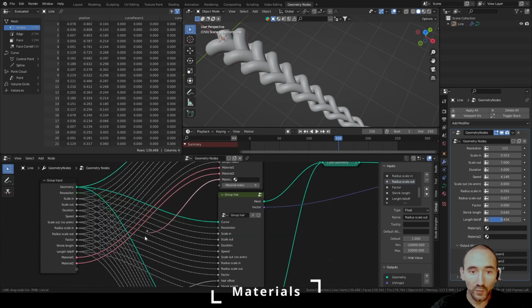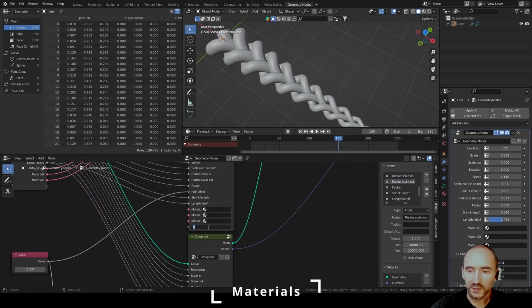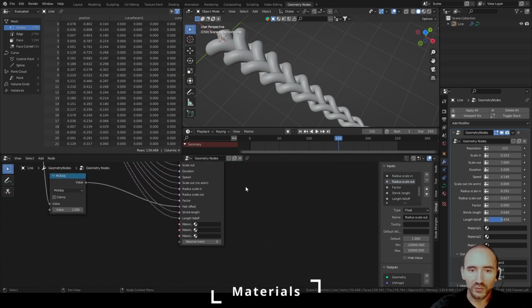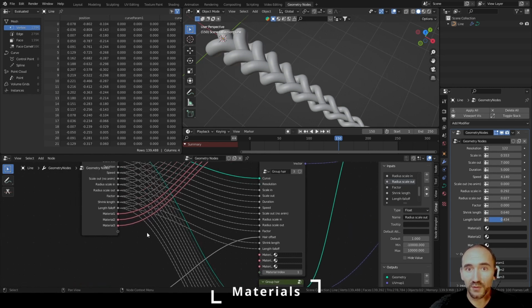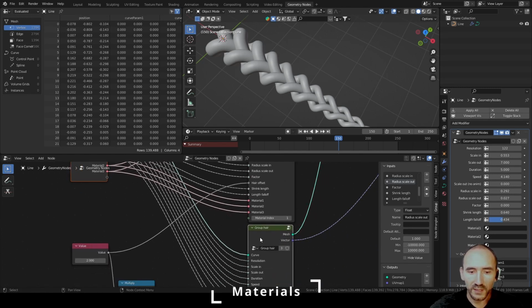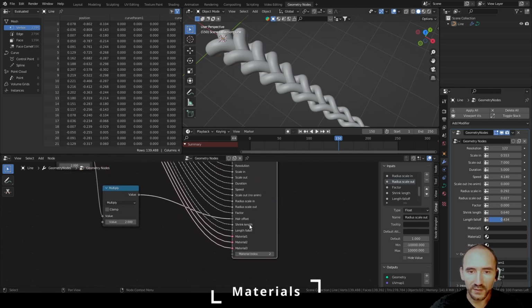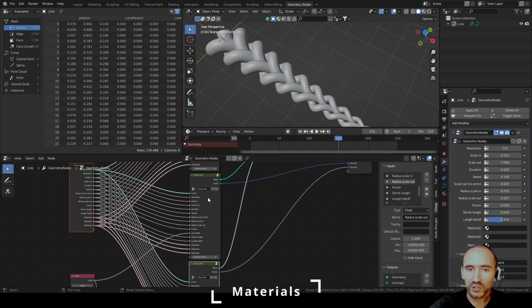We know that we want to assign the first material, so the 0 index of material, for the first branch, the 1 index, so the second material, to the second branch, and the second index, so the third material, to the third branch. I can click, shift click, FFF, click, shift click, FFF to link the three materials, but now the index is different, okay, for each branch.